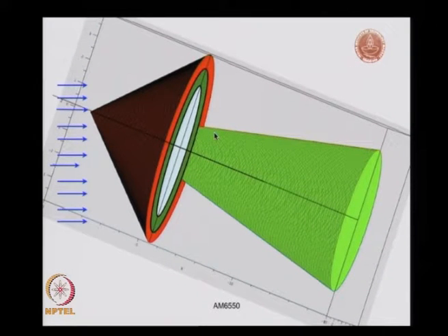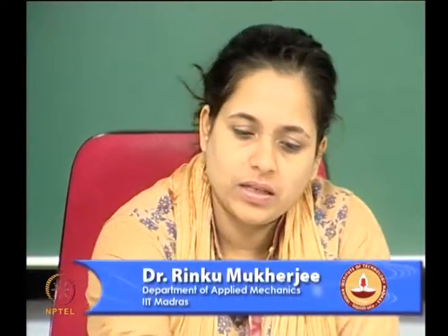So, this is my angle of attack, etc. And then we have these two streamlines, which will of course be along the cone surface, okay. And then you have the streamlines on the rest of the surface, which will be curled streamlines. Now, if you remember what we did one slide back, if this was axisymmetric, there would be no curling from the bottom to the top. They would all just be straight lines like this.